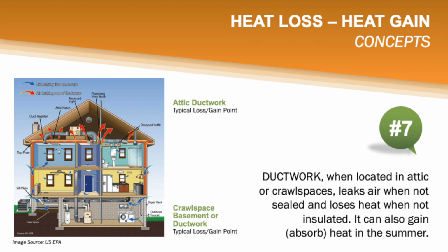For concept number 7, the location of the ductwork is the primary factor, and the condition of the ductwork an important secondary factor. We are primarily concerned with the ductwork's location. If it is located in an unconditioned attic, basement, garage, or crawl space, it will lose heat in the winter and gain heat in the summer. However, if ductwork is located within the conditioned living space, such as within walls or ceilings, we do not consider ductwork to be a source of heat loss or heat gain.